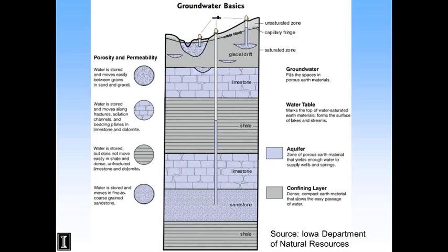And so when you have wells in the glacial drift at the top, again, if you're in an area that's unglaciated, you may have limestone close to the surface, or there may be loess or blown sand near the surface instead. So you can have shallow wells that tap into these thin sands near the surface, or maybe you're in a deeper well that has more capacity.